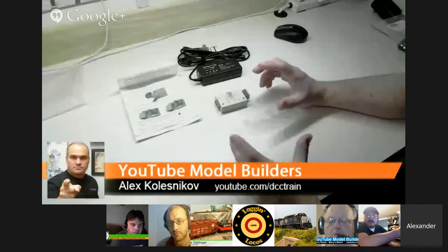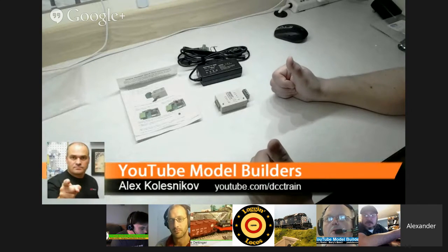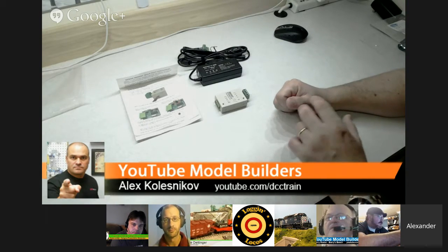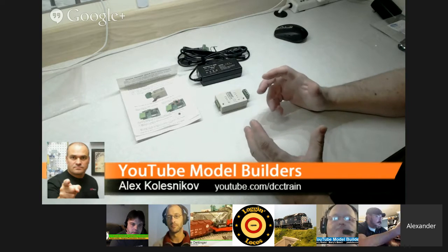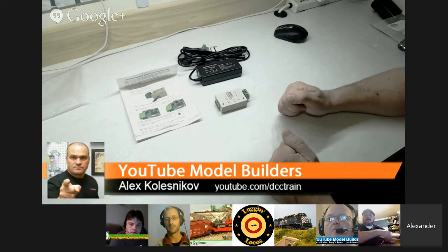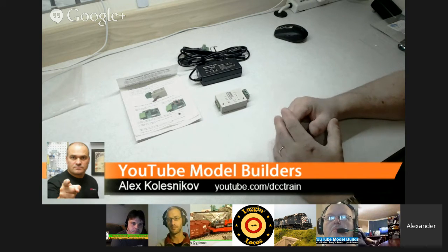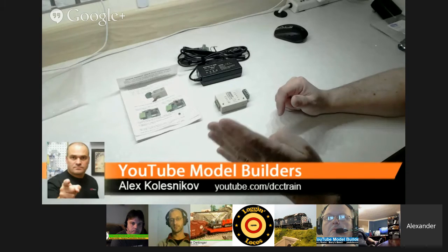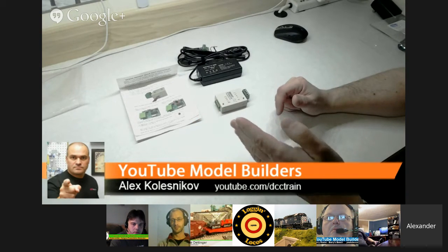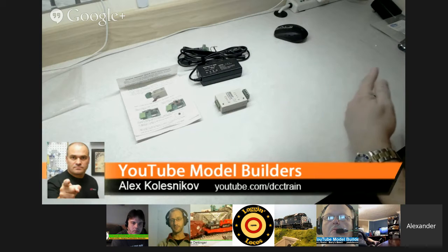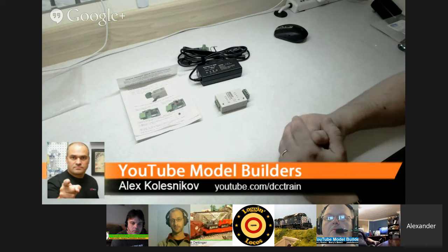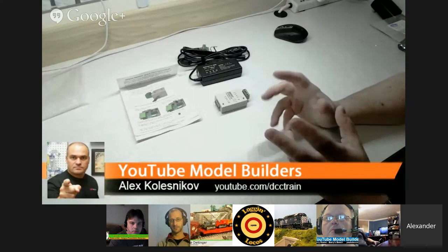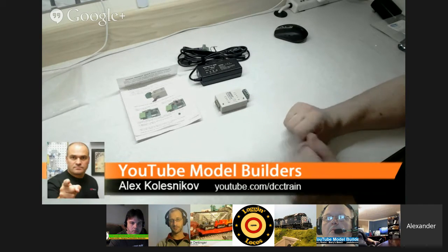Of course, modern LEDs take that away, but still, with a couple of engines with smoke generators running, it can be almost an amp pulling a heavy train behind them, so that's important. And maybe on your 100 feet of main line, it will be two engines just crossing each other, and as Barry said, your staging area or transition area will be completely busy, and you need to put massive power there.